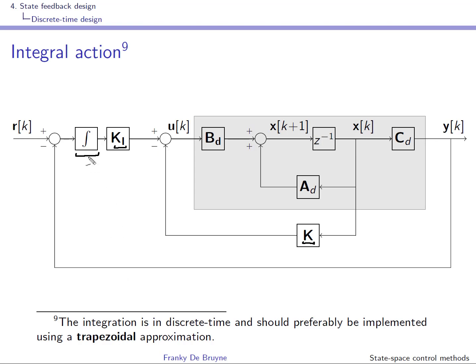The best way to implement the integrator, and you'll do this probably in Matlab Simulink, is to take a discrete time implementation of the integrator using a trapezoidal approximation, and this is really an integrator with transfer function Ts over 2 times (z plus 1) over (z minus 1).